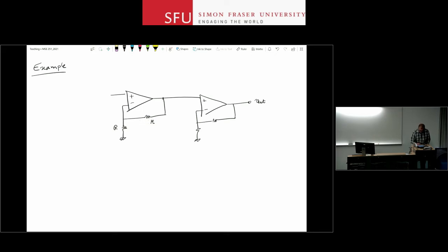Or if you're using a non-inverting amplifier, so this is 999 R, right? And then because the gain is 1 plus R2 over R1, this gives you a gain of 1,000, and this gives you a gain of 1,000. And you go from a microvolt level signal here to volt levels here. So everything looks good on paper.